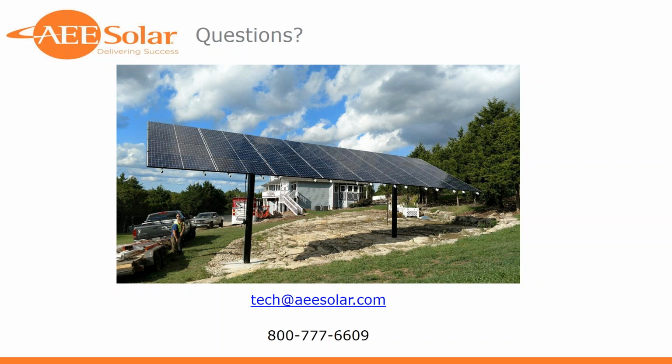Good question. I was not aware of that from Sunny Boy, and it's a little surprising, frankly, because with the new SA hardware, it's essentially what grid operators will ask those inverters to do. Through the use of local grid profiles, and I'm a SMUD customer, so let's use SMUD as an example, when the frequency or voltage drops, they're going to want the inverter to maintain full rated power. When the frequency or voltage rises, they're going to want that inverter to actively curtail.